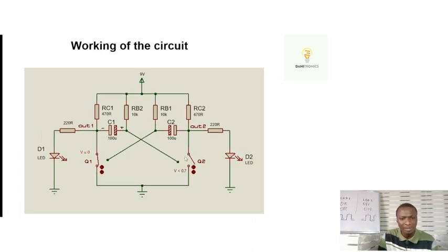Because this particular transistor is off and is open circuit, current doesn't flow through open circuit. In fact, current prefers to flow through a path of least resistance. So because of this open circuit, the resistance value is at infinity, is infinite resistance. No current is going to flow through this resistor, because there is no way it can flow through to ground, and current flows only in a closed loop. So current will not flow through this resistor to this point. Current also will not flow through this point too. So this is going to be the new direction of current.